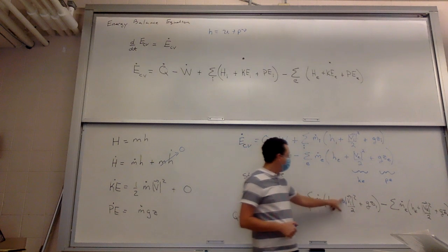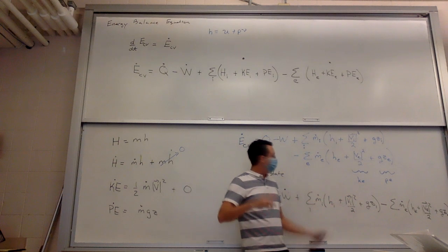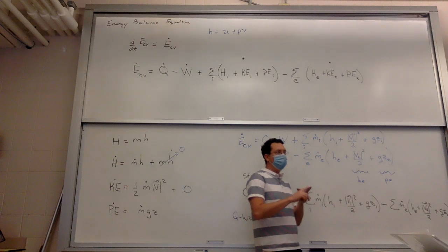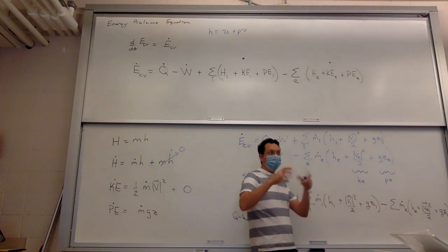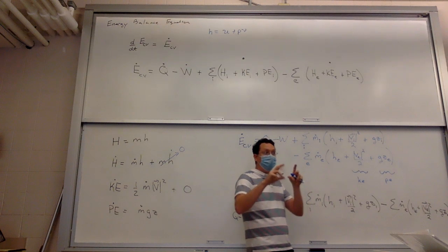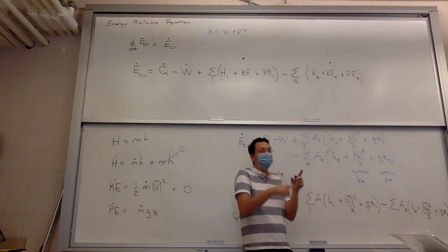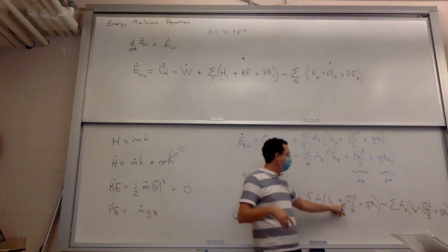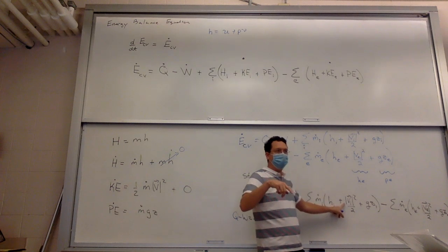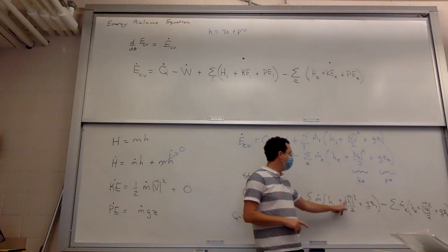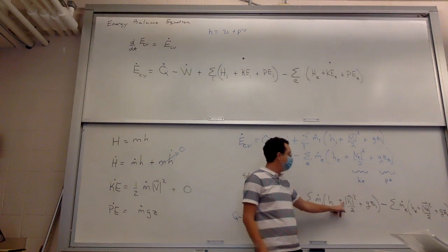And then there's a friction coefficient. The thing is, it's tricky because the number that you put there depends upon surface roughness, type of material, viscosity, and the speed of the velocity. It really depends upon the Reynolds number. So there's a whole art to getting the right number, and there are complicated tables. It depends whether it's turbulent or laminar flow. So basically, there's a fudge factor you put in there.